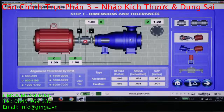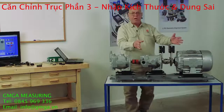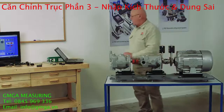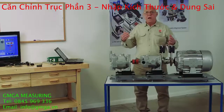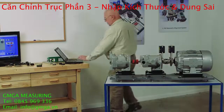Okay, we're just going to do a standard alignment for this one, and I'm going to have to give this some dimensions. Now another feature of this is the way I'm viewing this, the motor is on my left side. That's the way I'm doing it here. But if I was on the other side, the motor would be on the right. So I could just simply double click this and change the side that the motor's on. So I want to view this the way I'm looking at this. Just makes life a lot easier.